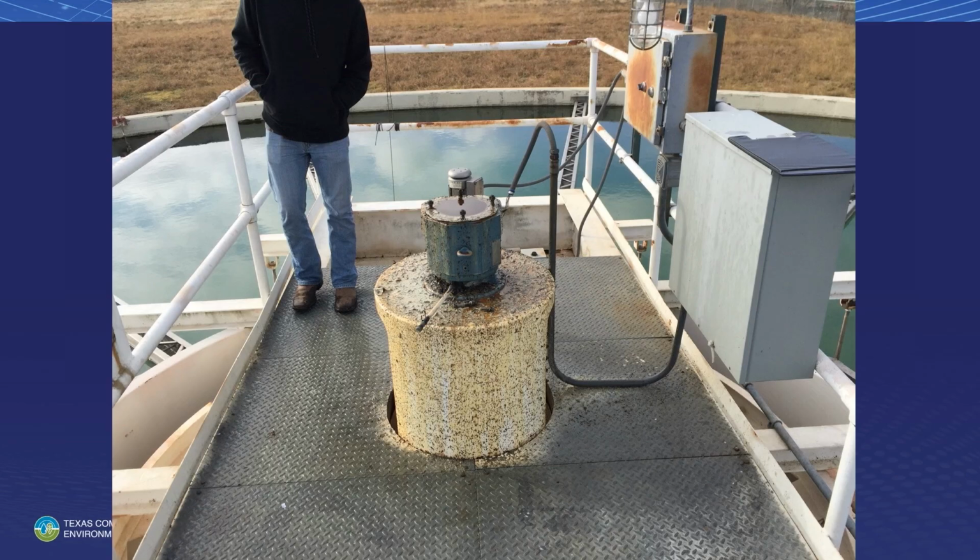Let's see, I'm here at the top of this clarifier, and the superintendent of this water system is trying to explain to me how this upflow clarifier is really an upflow clarifier. He was basically running a sludge blanket unit where the sludge was building up high enough on the outside of that cone that he was getting some kind of flocculation and sedimentation based on that water coming through the blanket.